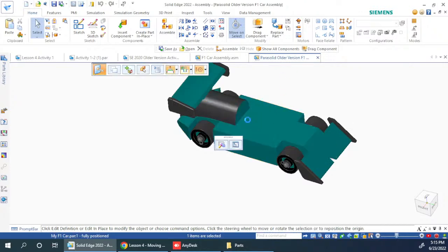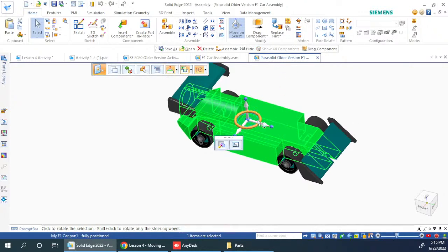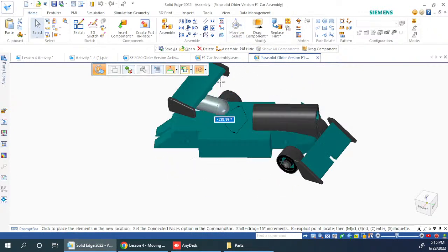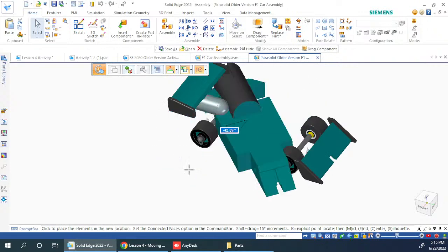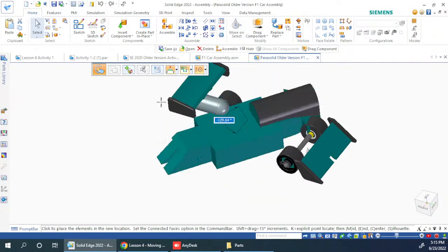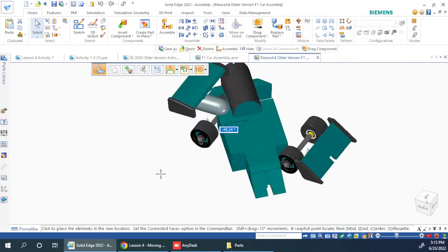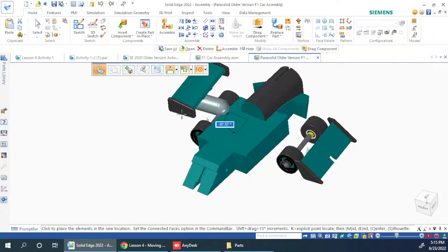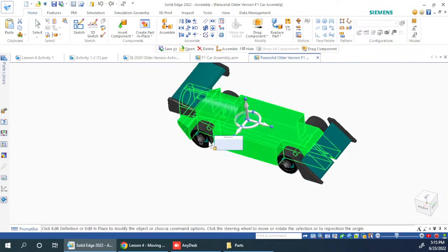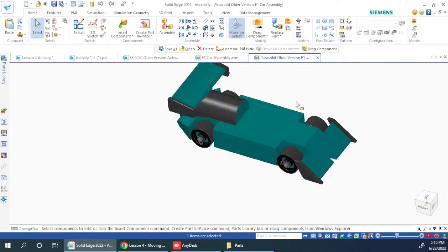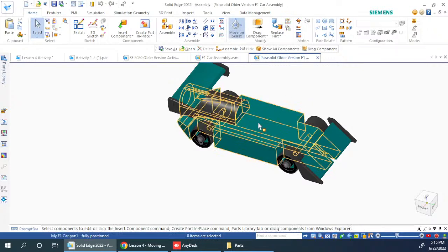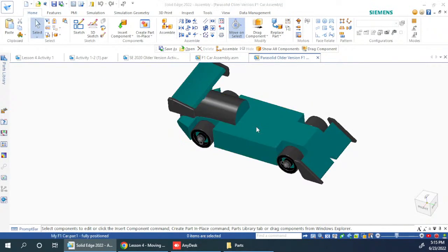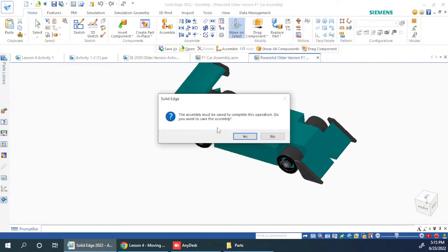If you want to make any changes to this, you can use the steering wheel once again. If you are moving any part in the assembly format, you can see the whole part is actually moving. Suppose you just want to edit any of the faces. Suppose you want to edit only one of the faces. Then what you have to do is first open that particular object.